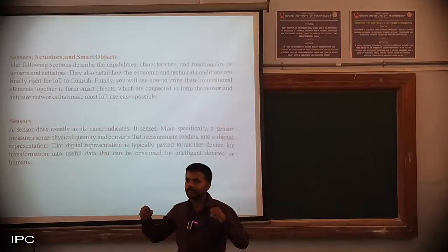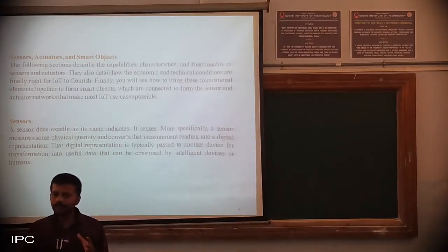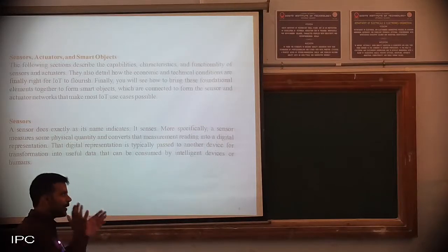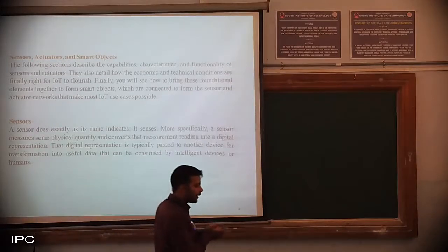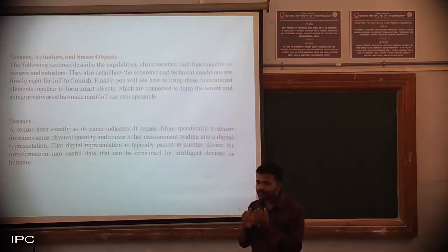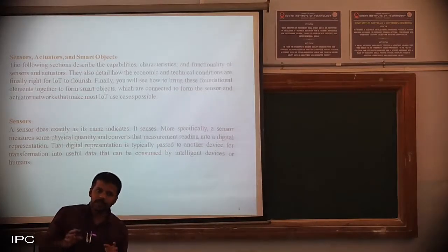If the room is not occupied, the sensor sends information to the microcontroller chip, which analyzes that nobody is in the room, then generates the input and sends it to the relay. The relay trips the circuit, and the electrical appliances inside that room will be disconnected.